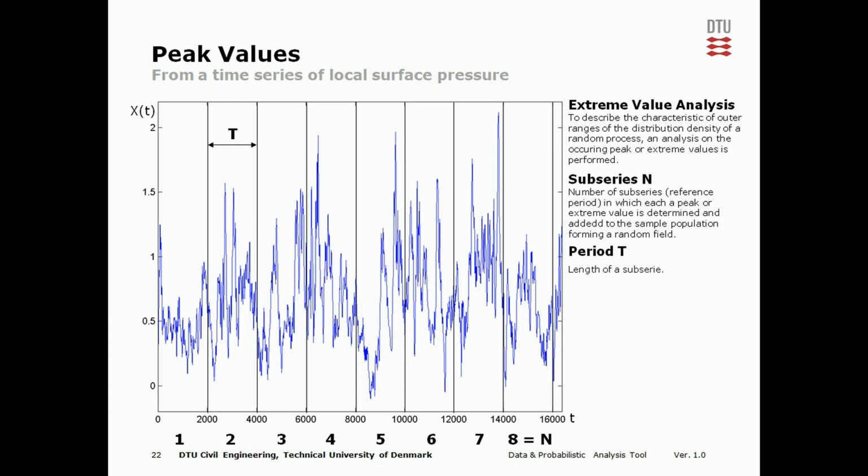The length of each data set should be sufficiently long. It should be long enough to represent the characteristics of the overall loading, so that we don't have loading events which are significantly lower than all the others, which would not be suitable for collecting peak values for the characteristic value. This again is the idea of ergodicity: all the subseries should be equal to each other in their characteristics, but of course in their particular variation they differ from each other.